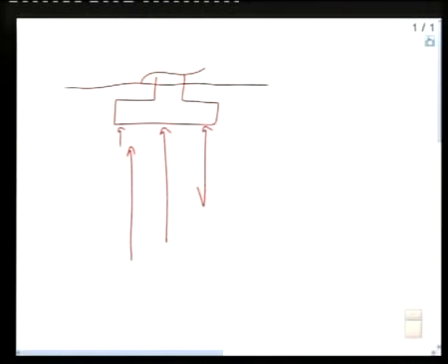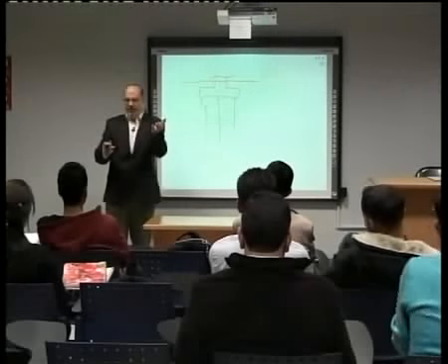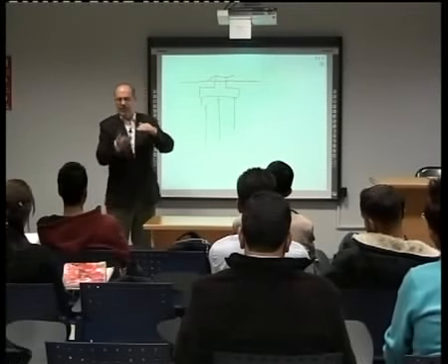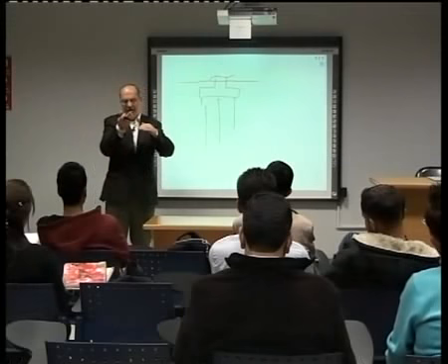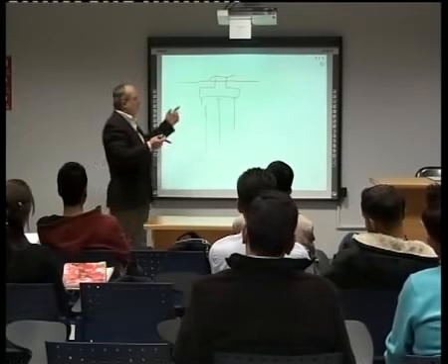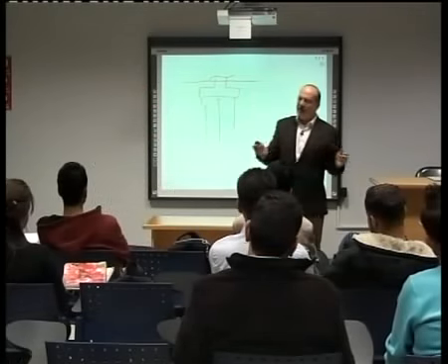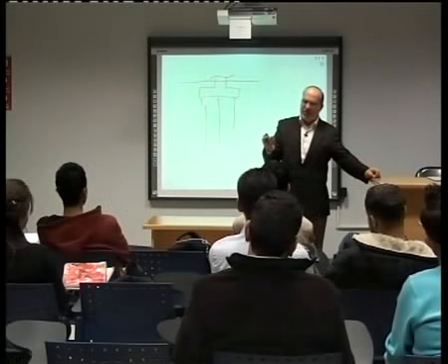Then what will happen? It will pressure the foundation, right? If the foundation is not heavy enough, then it will go up, right? And of course, when it goes up, this will affect all the structure, and a collapse, a failure may occur.